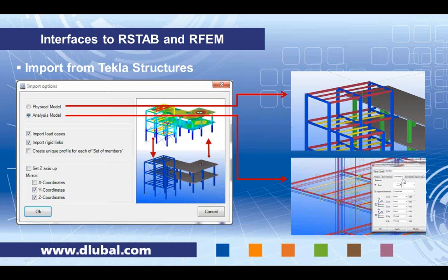Inside Tekla we have access to information like how a beam is connected to a column. Is it a moment connection, or is it a pinned connection? And I can set the degrees of freedom. Typically this information in architectural software is of no relevance.